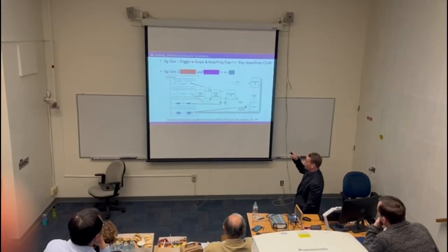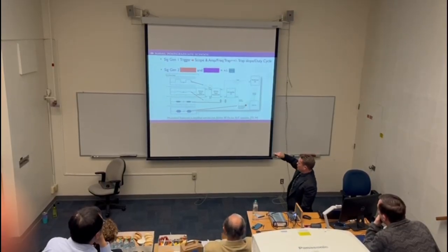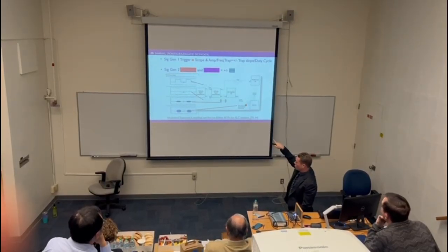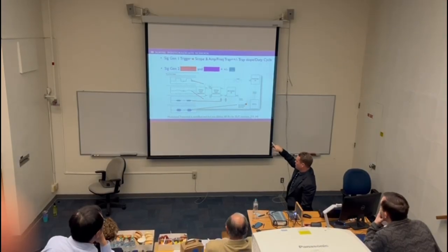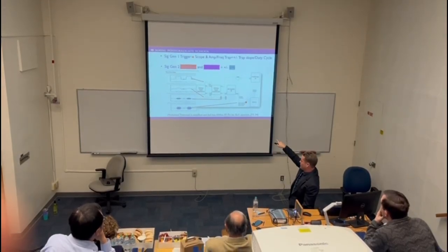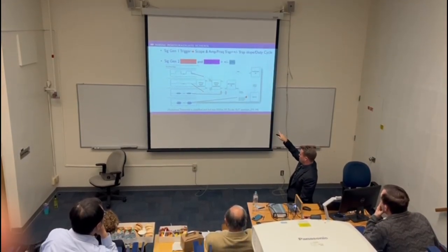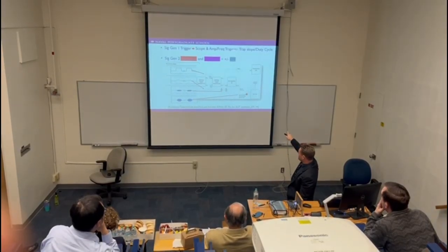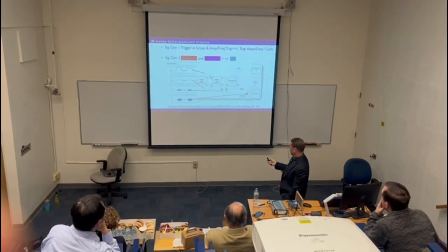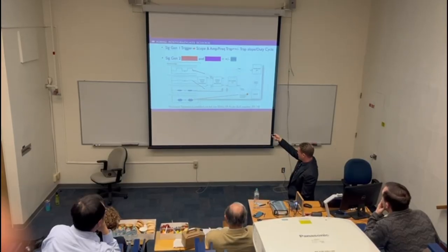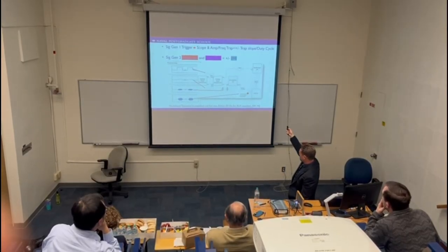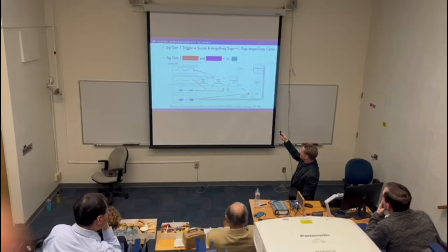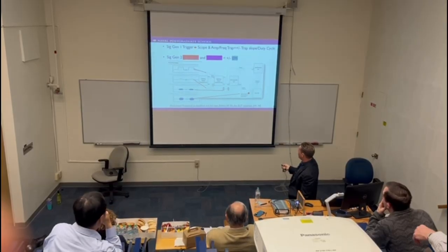And it's twofold. If I look at signal generator 1, I'm creating this trapezoidal envelope. That trapezoidal envelope modulates a sine wave. Then that modulated sine wave is injected into the equipment under test. And again, with signal generator 2, I'm increasing the amplitude and frequency to change the amount of EMI. Signal generator 1 is creating that modulated envelope.